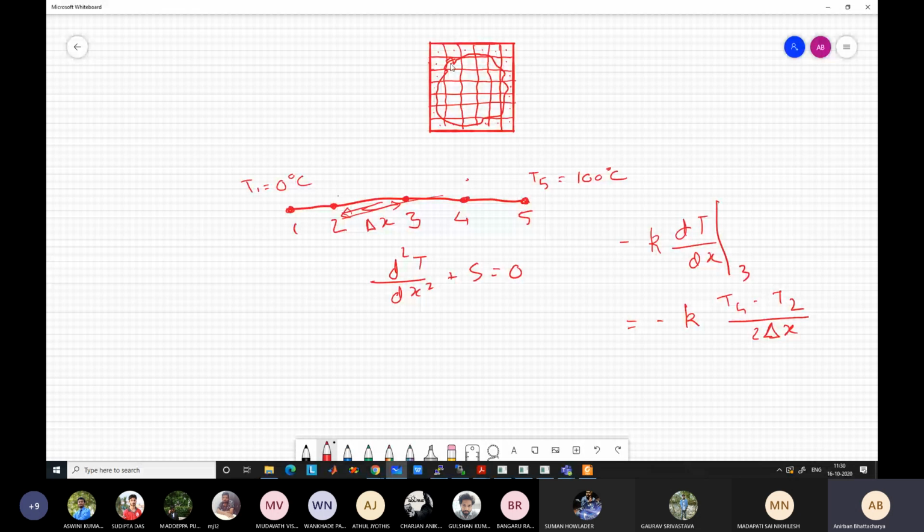Another thing, then you will have to assume either the grid point is inside the wall, meaning the control volume, or outside the wall. You cannot resolve it properly, so your boundary will look something like this, jagged, staircase like, because you are unable to accurately capture this. There are other ways to tackle these things, but I am saying from a simple point of view. So you have to take a very fine mesh, otherwise your boundary will look like a staircase kind of.